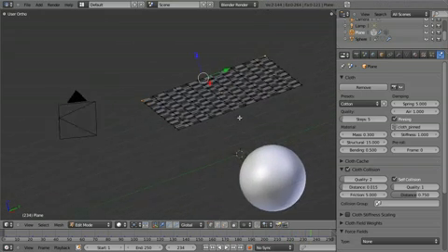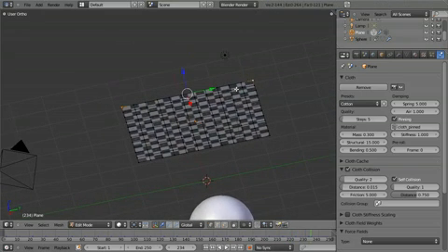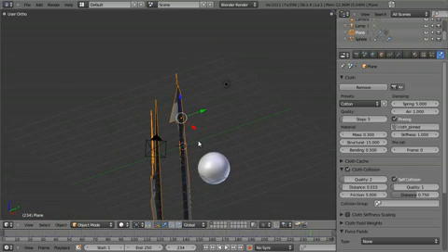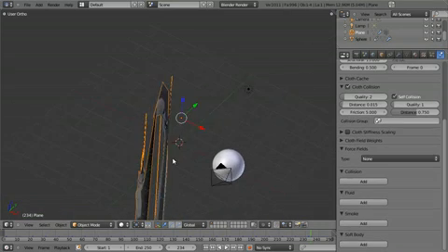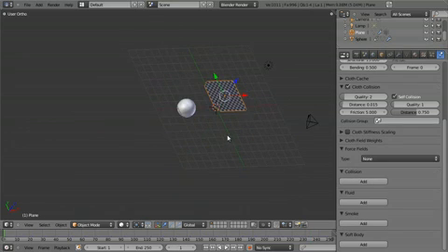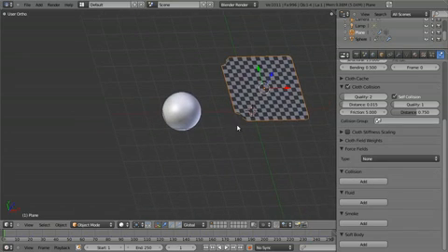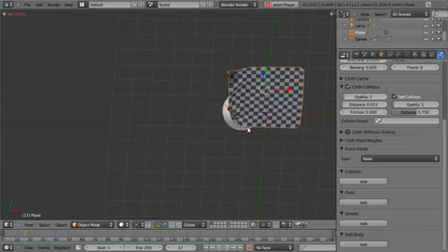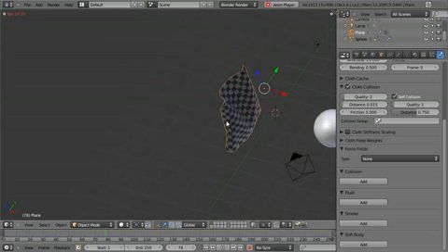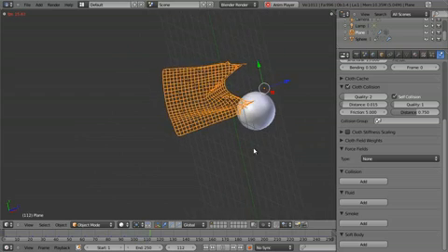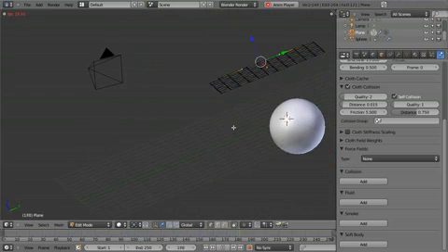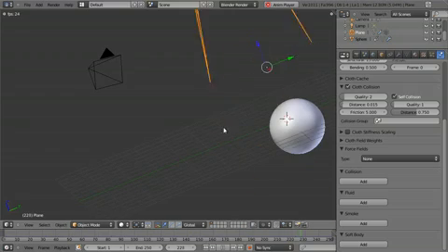And we can maybe see this a little more clearly. Let's say we grab these two edge vertices and slide them in to the edge here. Now, obviously you can see that when you do that, it messes up the simulation because it just goes haywire. So go back to the beginning of your timeline by hitting Shift left arrow, and then let's play this. And so now you can see that it's no longer intersecting with itself, but it's folding over, no problem, and really working quite nicely. Let's hit Tab and undo that in edit mode.